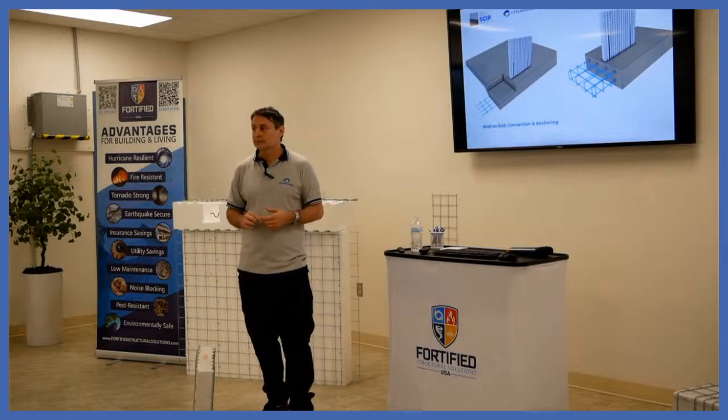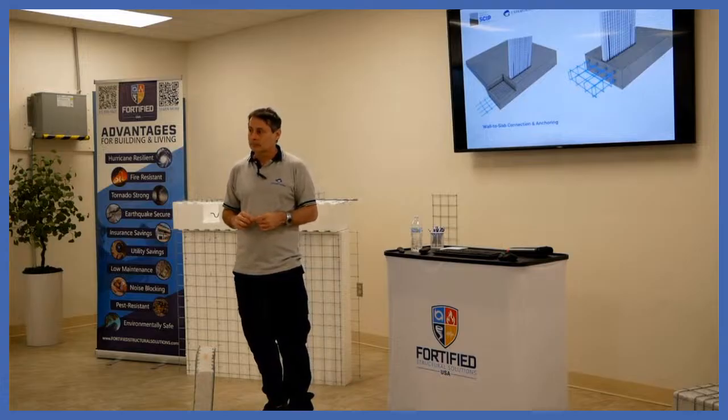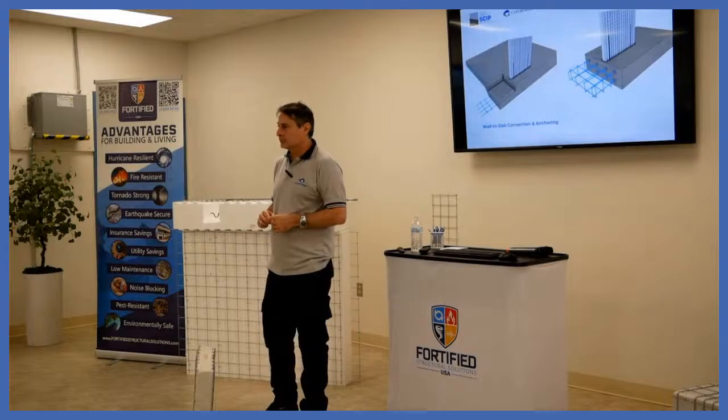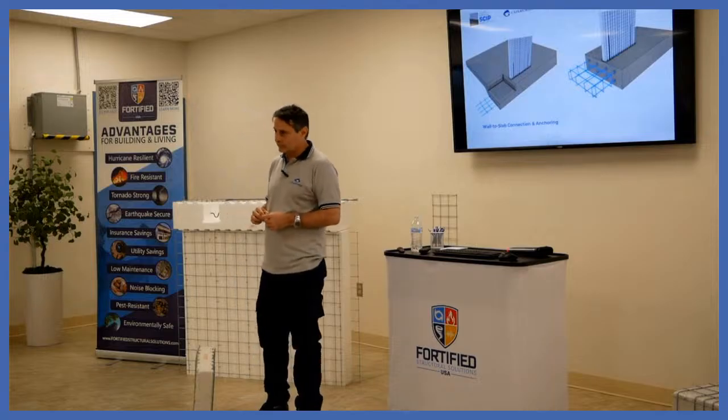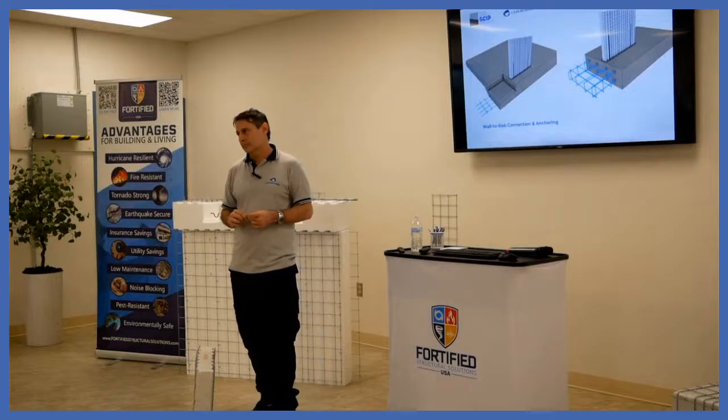What I would say is that trying to design by material science will never get you to the capacity these panels are capable of. By far, the best way to do it is with physical testing, and capacities of beams and so on are available.